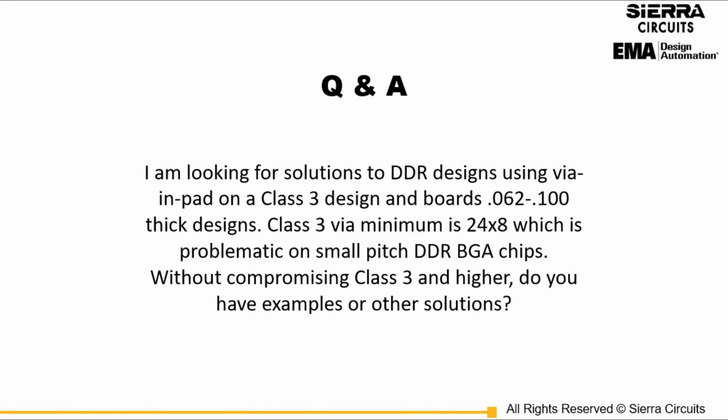I see the first question is about the actual physical pad size, the minimum hole to pad ratio for class 3 products. Designing with the tighter pitch devices is truly a problem where you have the pitch. Again, work with your fabricator on that to see what can be compromised as far as the class 3 products.